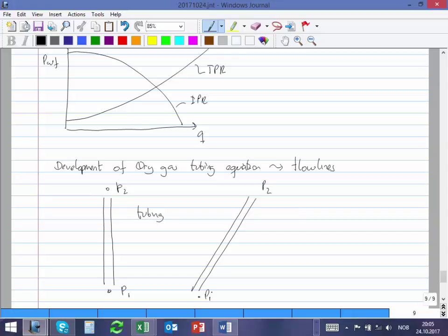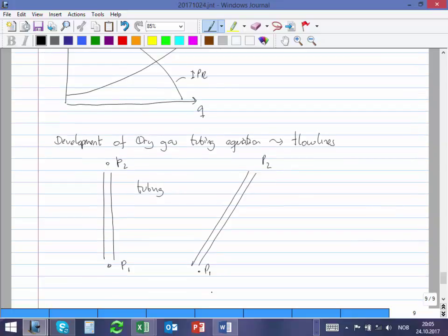Okay, for any flow line. And then you ask me, for example, okay, Milan, very interesting, but our wells usually are like this, and then I have a section like that, and then a section like that. So how to deal with that case? What you're going to teach us is for just one inclination. What is the answer? Okay, this famous guy, what was it, Caesar? He said, divide and conquer. So in that case, you make one equation for this segment, one equation for this segment, and one equation for this segment. Okay, 3 equations, but you use the same equation. No problem with that. So that's divide and conquer.